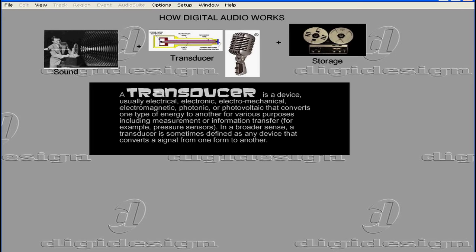With analog recording, like tape recorders, an electromagnet realigns magnetic particles on the surface of a moving tape. This varies the intensity of its magnetic field in response to variations in the incoming voltage. That's how the electronic version of sound waves gets stored. The magnetic stuff stored on the tape is converted back to voltages through the amp and speakers. The result is fairly analogous or similar, hence the name analog recording, to the original signal.